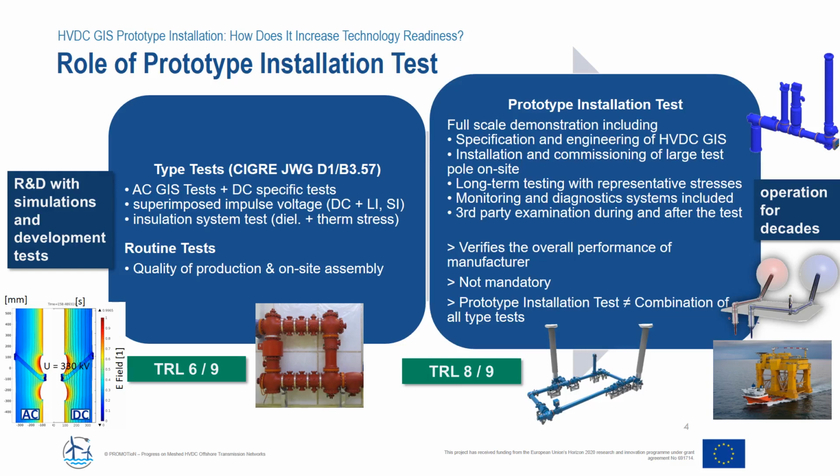It is a full-scale demonstration, including specification and engineering of an HVDC GIS installation, the installation and commissioning of a quite large test pole, on-site long-term testing for more than a year with representative stresses, dielectric, thermal, mechanical. We have monitoring and diagnostic systems included in the test pole and third-party examination of all the steps.